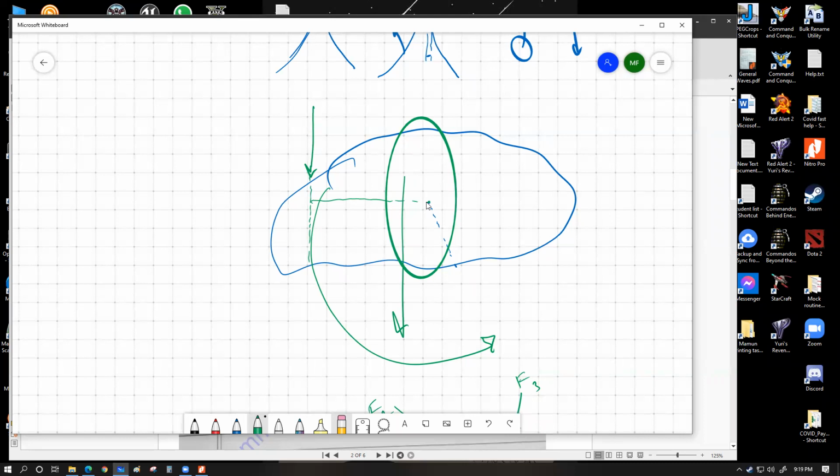Try to think about it. If you have a freely suspended object that is experiencing an ongoing moment on itself, which is not stopping, every single second the moment is going to cause the object to speed up or spin faster. So, point to be noted, a visibly rotating object can be in equilibrium provided it doesn't experience any resultant force and doesn't experience any resultant moment.